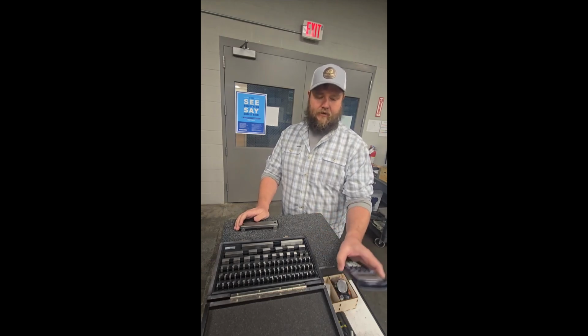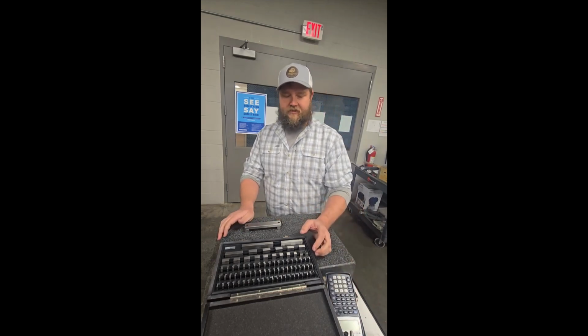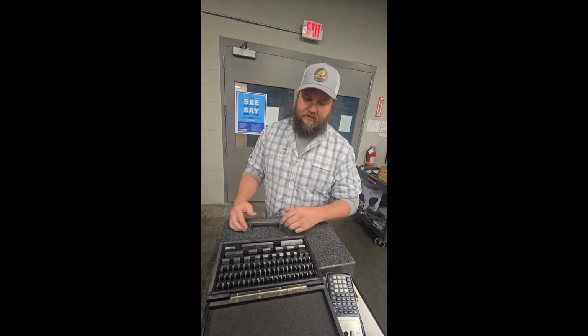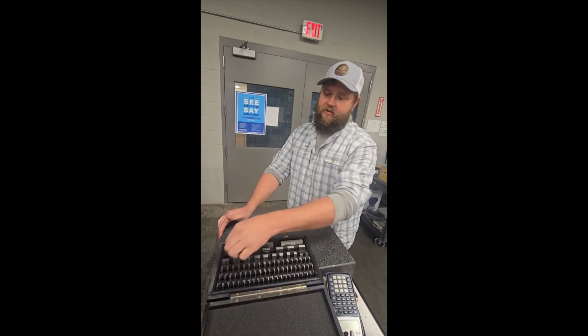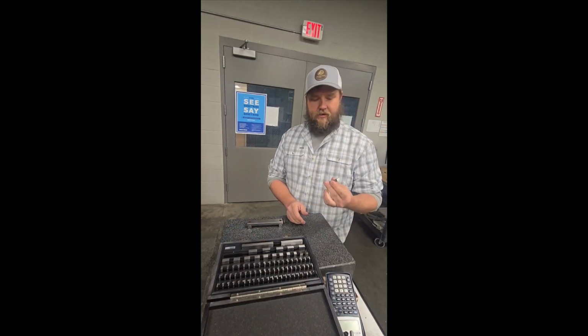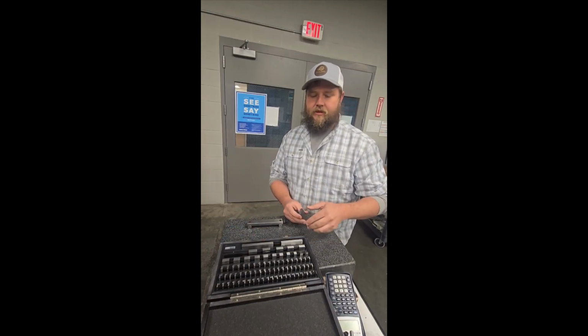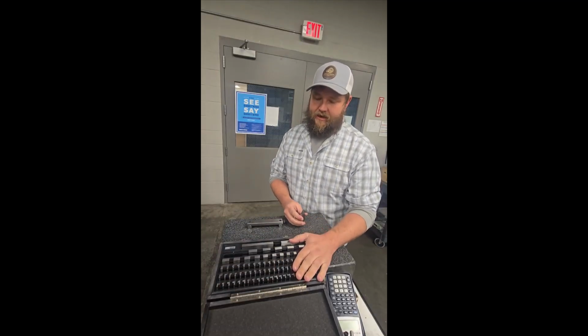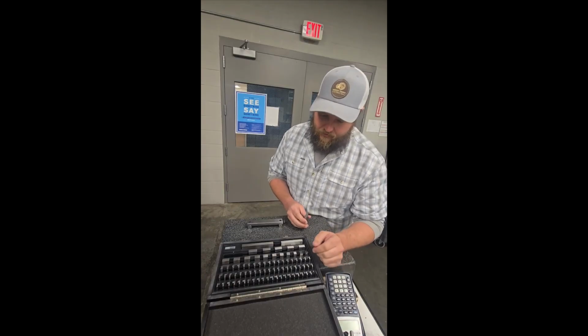If we wanted to use 30 degrees, since the sine is 0.5, we can multiply that by our 5 inches, come up with 2.5 inches to stack under it. And to do that, with the gauge blocks, you can create different measurements based on stacking them, and to stack them you do what's called ringing.